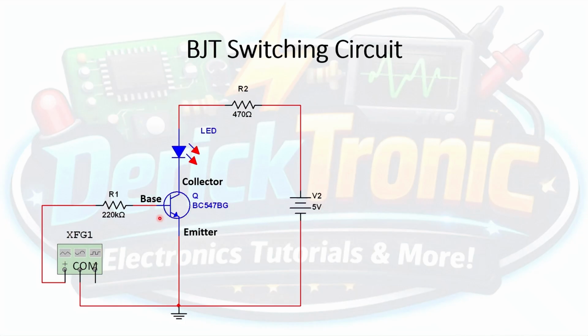Now, on the base, we have a limiting resistor, R1 here, 220 kilo ohms, and that resistor is connected to the function generator. Both function generator and DC power supply will be connected to a common ground where the emitter is also connected.